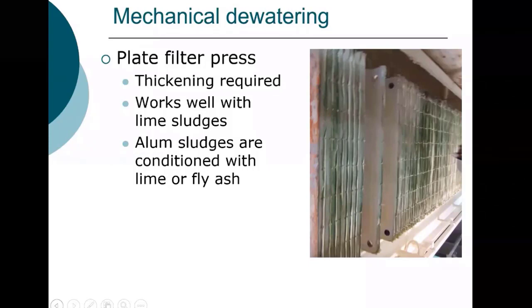And that pressure is maintained for about 1 to 4 hours before these plates are opened. And what you're seeing is the process here of the plates actually opening. And then in the next video, you'll see the sludge actually falling from the plate filter press.